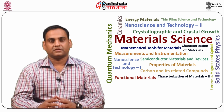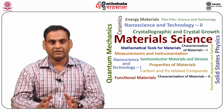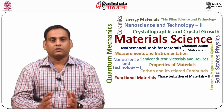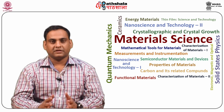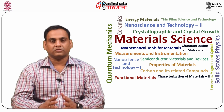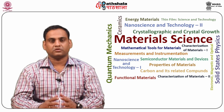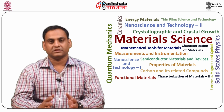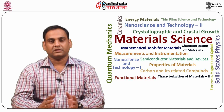Soft magnetic materials. Most of the magnetic materials of industrial interest are ferromagnetic materials. The ferromagnetic materials can be categorized into two: one is soft magnetic materials and another is hard magnetic materials. A ferromagnetic material in the demagnetized state does not show magnetization, although it has spontaneous magnetization. This is because the ferromagnetic material is divided into many magnetic domains. Within a magnetic domain, the direction of the magnetic moment is aligned.